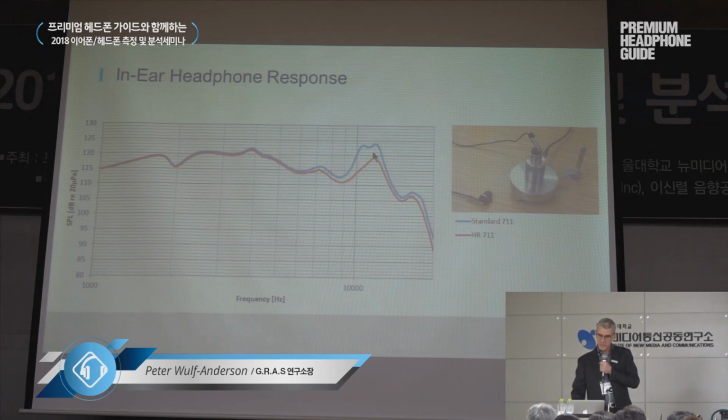We can see the result up here around 10K is very different. And the ear simulator resonance is what's affecting the measurement at this point here in the old analyzer, and we can see in the new one that ear simulator resonance is almost not there.